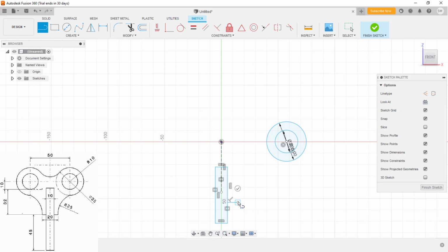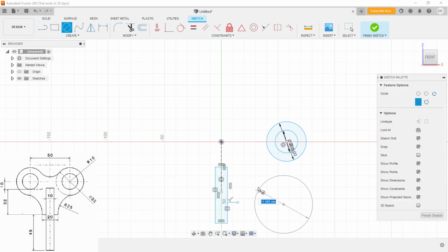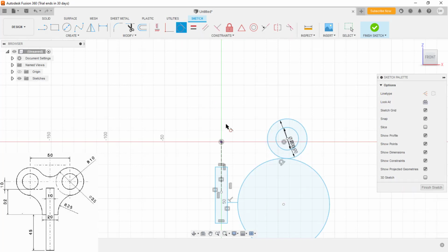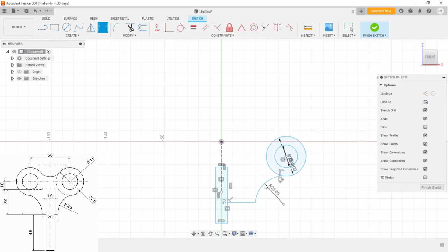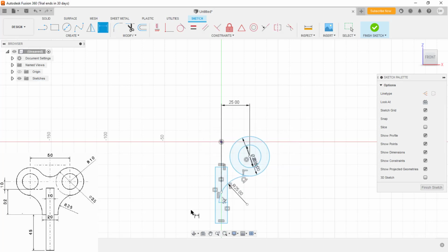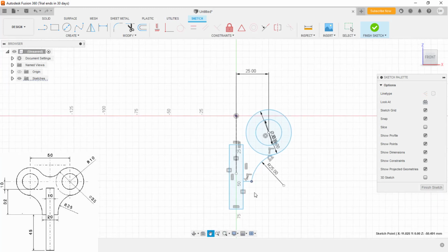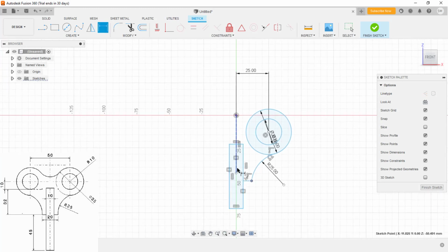You can draw a line here, simple one. A dimension I don't know at the moment, let it be. I need the, yeah, circle is fine here. Hold the control, tangent, done. Trim it. The radius is given 25. Now from this center to this construction line, origin line is 25. Yeah, now it is moving inside, so escape, drag it out like this. This is fine. Now the total length of this from here to here is given. Mention the same thing, it is 10.